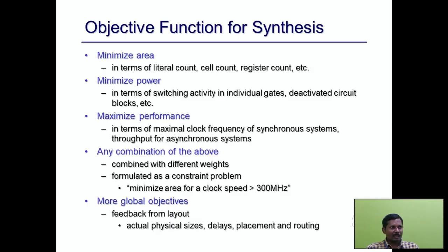Objective functions for synthesis. One is to minimize area. Minimize area means minimizing the count. As I said earlier, the logic gate count, cell count, or register count, or some modules may be merged with some other module. So as a goal, we need to minimize the overall area of the particular design.